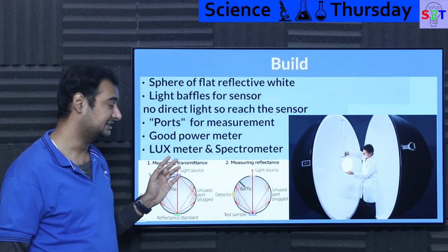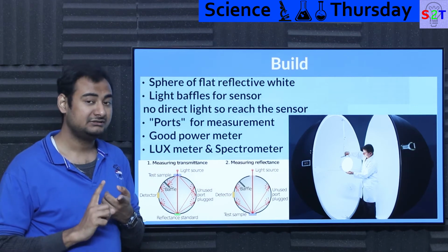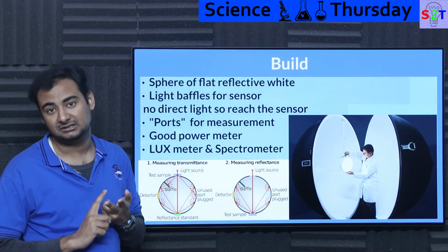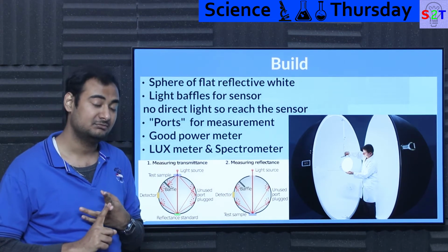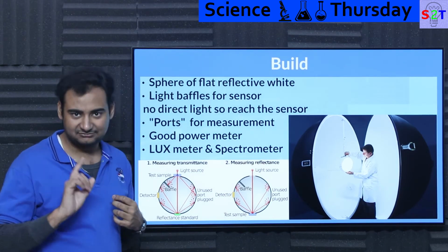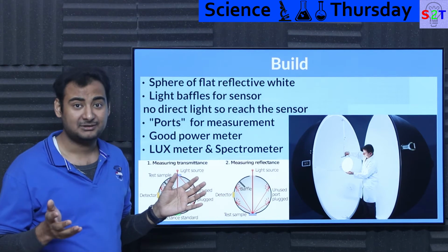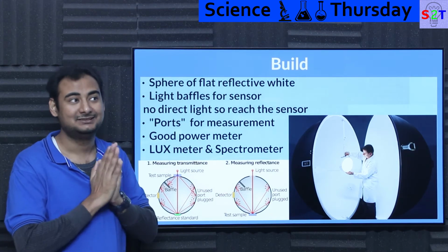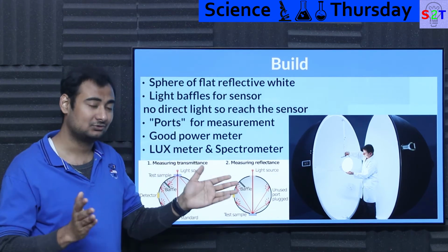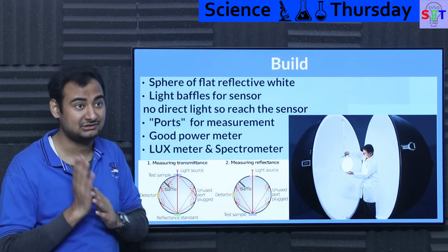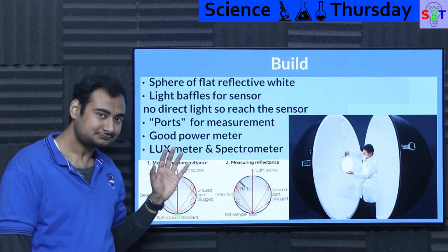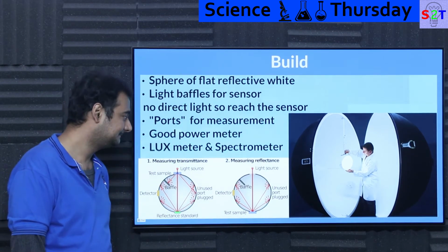The better, basically even for an AC system, not only voltage and amps, you also must calculate the VA rating, meaning power factor must be accounted for. And that's the worst part you have to understand. Many cheap LEDs have really bad power factor, generally 0.5, so they are really bad. You would be surprised how close it is to a filament lamp because of the bad power factor. So these are generally the build behind it.